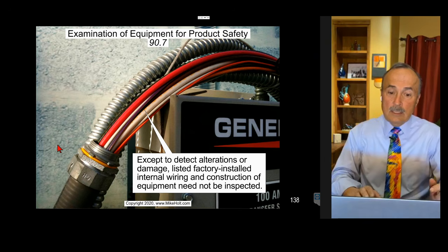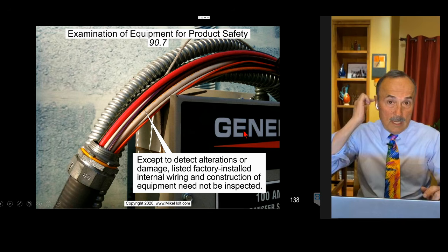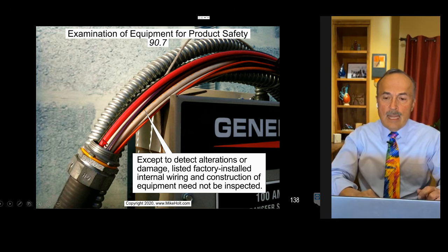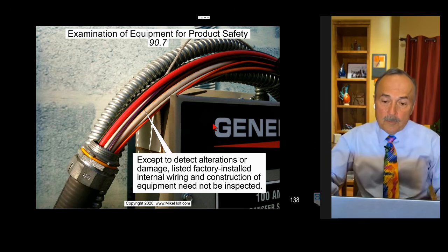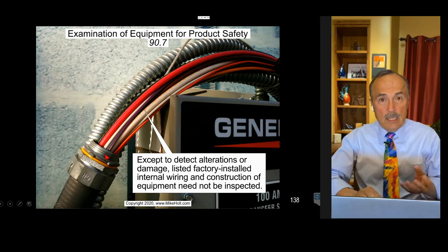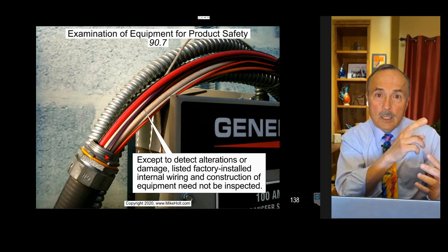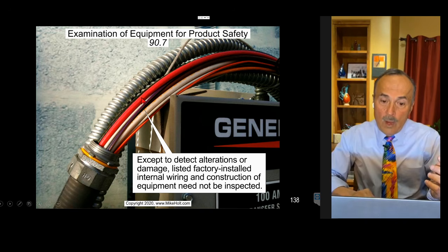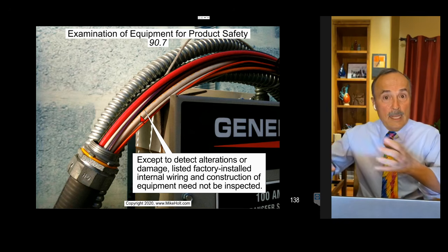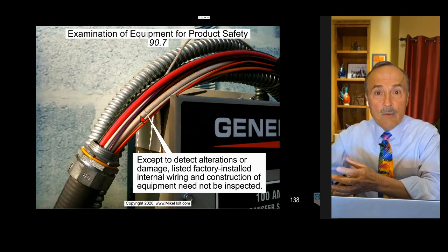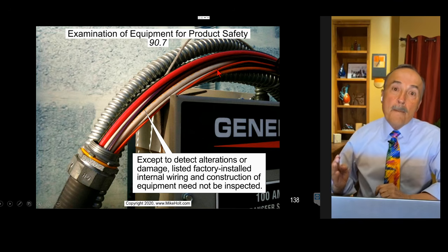Look at this example here. Here's a Generac. I can't remember exactly what this is called. This is called a generator transfer panel. So you take this wiring here and you connect it to the panel, and you take wires that were going on a breaker in a panel and connect those wires to some of the wires here, and it goes to the generator transfer panel so that it can get power, and then the transfer power goes to these conductors, and then you have conductors going back.